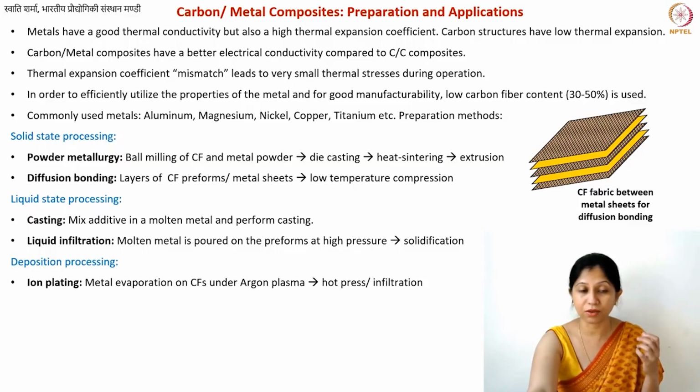So you evaporate a metal at lower pressures or higher temperatures. These kinds of techniques, evaporation and sputtering, are actually rather common in microfabrication. They are often enhanced, supported with plasma, for at least a little bit of impregnation of the ions. This is why it is known as ion plating. So you're doing plating, but you want a very good adhesion. Not impregnation in the same way that you do doping. No, that's not your goal.